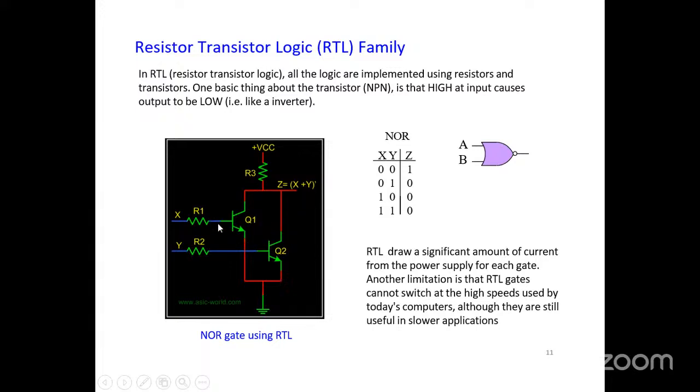The transistor is basically used for two applications. One is as an amplifier, and also the transistor is used as a saturation on-off switch. When the transistor is operated in the active region, it can be used as an amplifier. Suppose you want to use the transistor as a switch, if it is used between the cutoff region and the saturation region, then it acts as a switch.